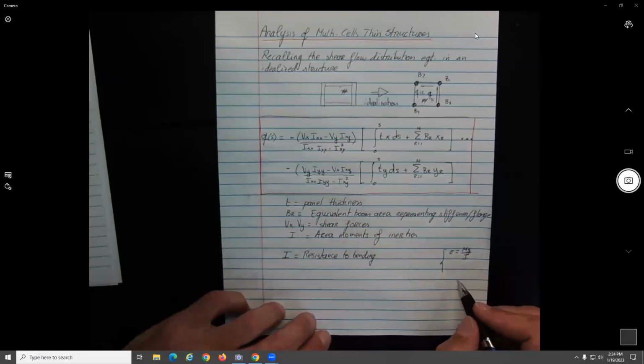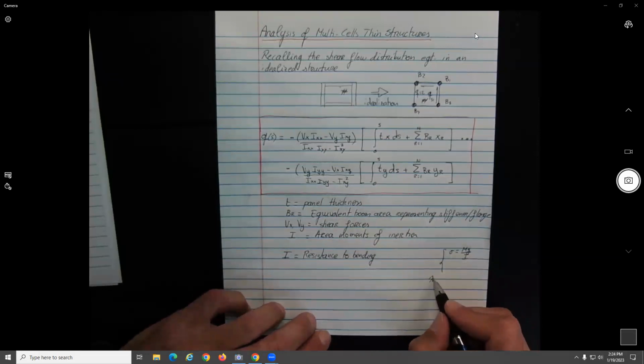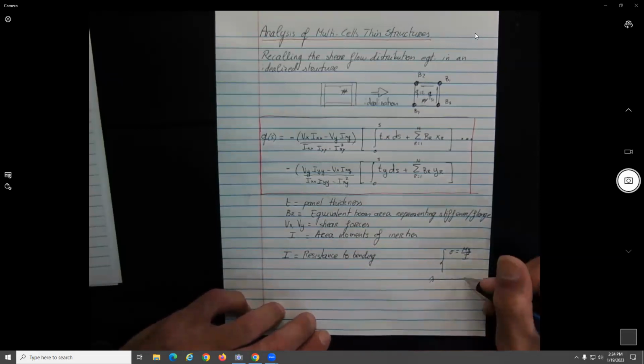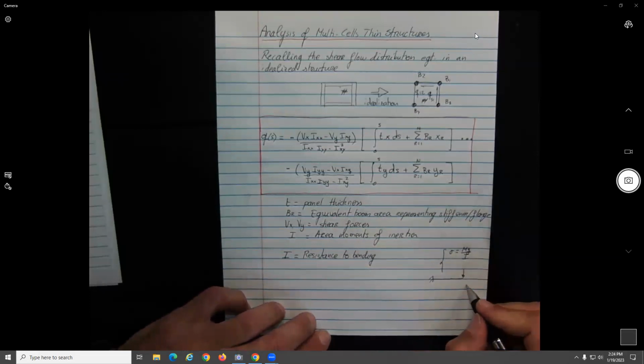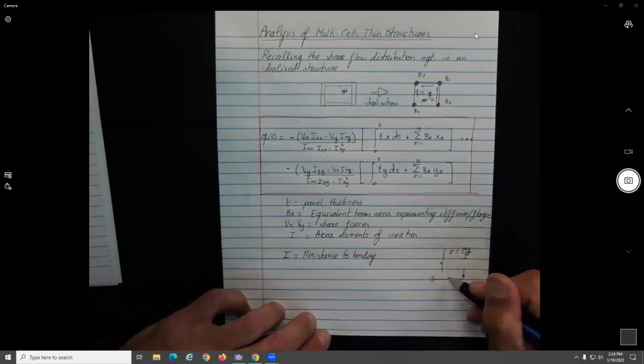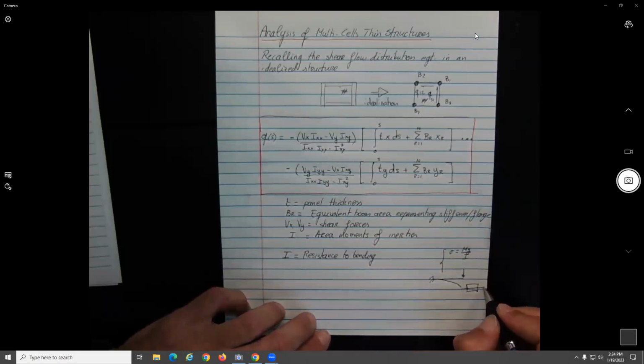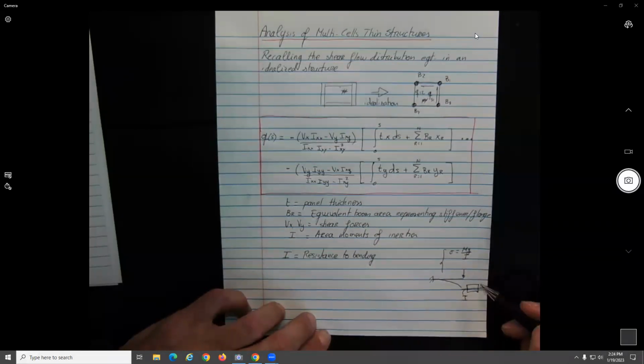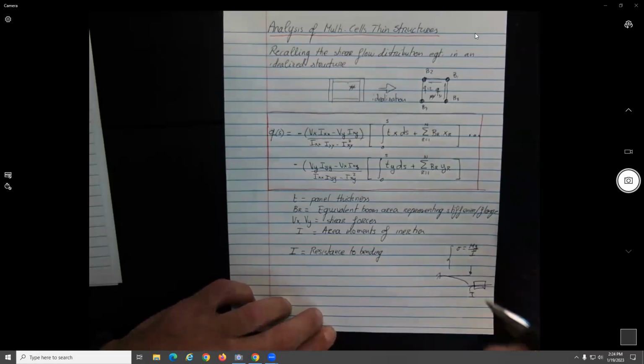So, for example, if you have a beam that is this way here, let's say you have the load over here. Let's say you look at the cross section of the beam. So this is going to bend. How is this going to bend? Let's say it bends this way. What is the I that you take? You take the I between these axes, no? So the I of this axis here. The higher the I is, the more the I represents how unlikely this surface is to rotate about this axis. You want resistance to bending.